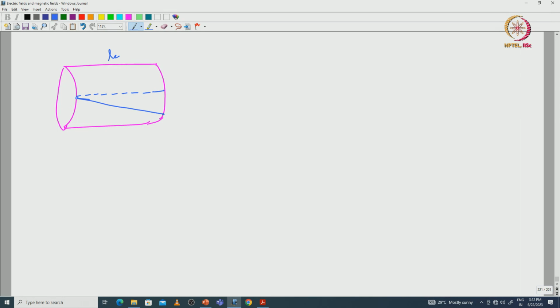The skewing angle is nothing but the angle from the starting point of the bar to the angle which is going to the other end of the bar. This is the skewing angle alpha, is nothing but skew angle, and which is represented in terms of stator slot pitch or angle.